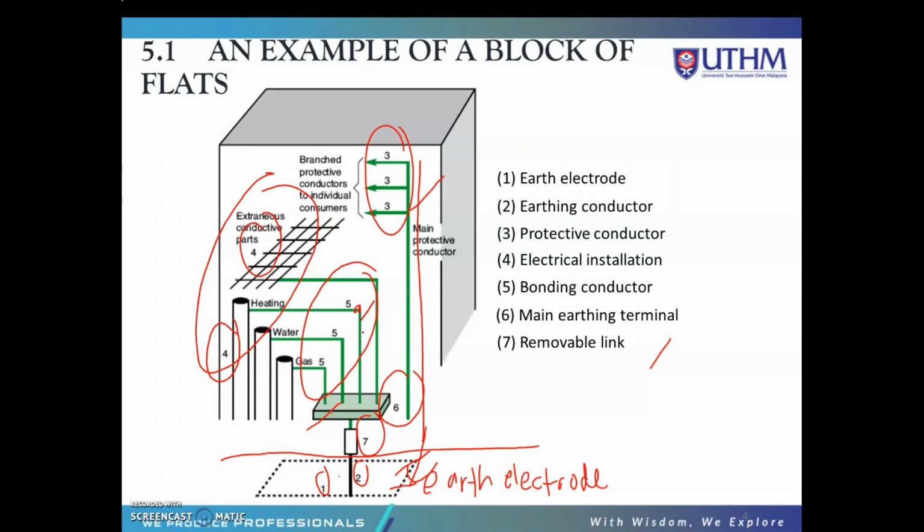When all conductors are at the same potential, no discharge can occur. So the purpose of this bonding is to make sure that we have the same electrical potential between the person, surface and product with the earth.